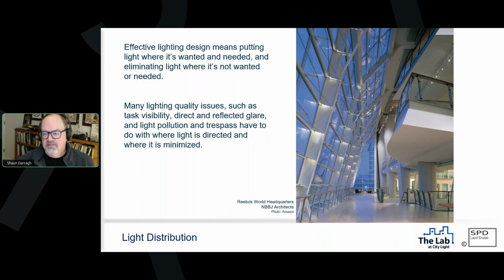So in this particular case, this is Reebok World Headquarters back in Massachusetts. There were a couple of key things that I wanted to do here. This is a connecting spine. It connects 4 different office buildings together, and has a lot of different functions going on. But one of the things you'll notice is that there's basically almost no light at all lighting the floor. It's all lighting surfaces. I have accent lights grazing up the structure. I have accent lights lighting the column knuckles here. I have accent lights lighting the building structure, and that's predominantly it.